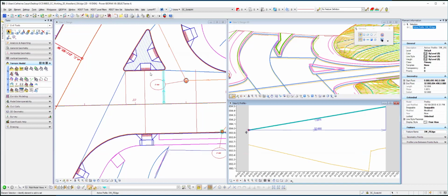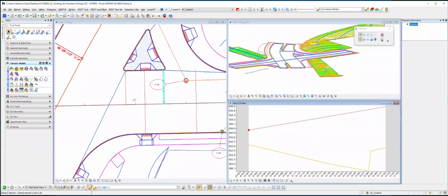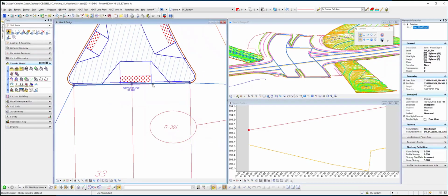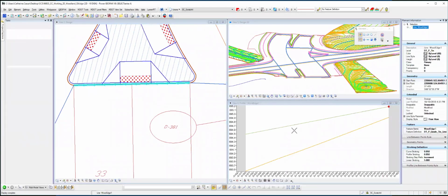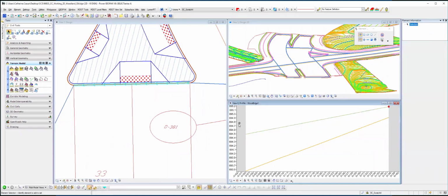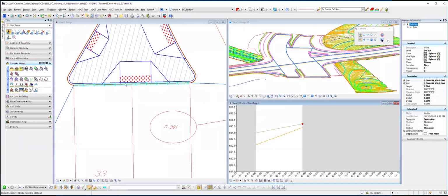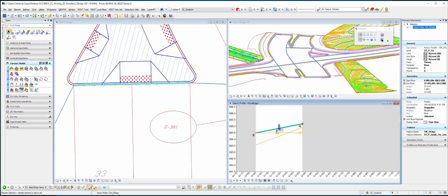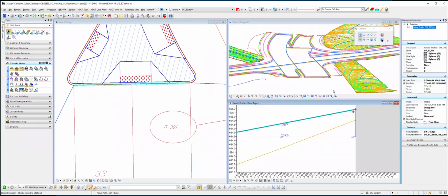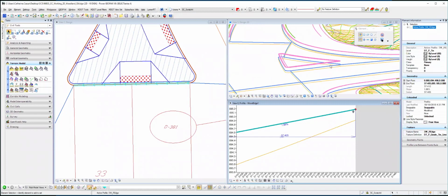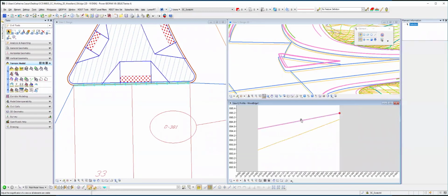Oh, okay. So then you just drew the vertical line in there, but you didn't set it active, right? That's just so you can see what the percent slope is. No, it is active, so I could then see what was happening here across this island. Okay, so this is smart geometry, and I wanted to see what was happening. So there's a point there. It's really tiny. So I'm snapping across these lines, and I could see what I had as a slope, and that became the slope for that island. Okay, so I used them to control this island, but these lines themselves are not in my terrain model. You don't see them in here.